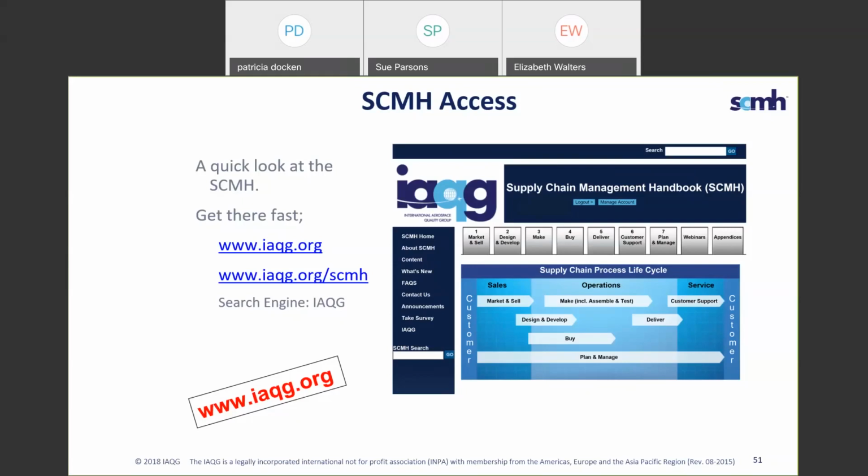All right. Our customers only require a control plan for new product or part revision. Do you recommend doing a PFMEA every time a control plan has to be done? I think that's what you kind of said. Yes, it really is a key input into a control plan to have the information from the PFMEA.